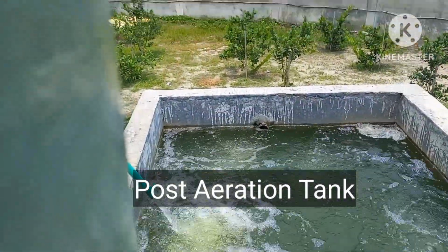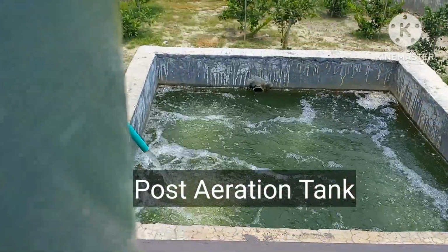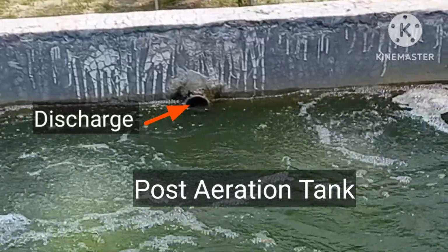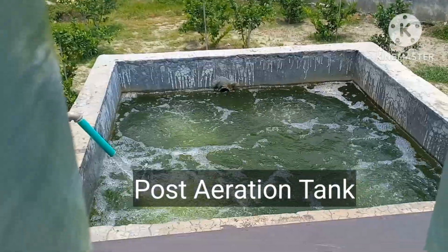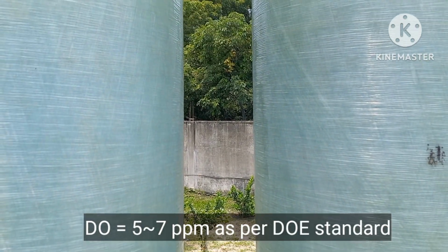After filtration, the dissolved oxygen is low and cannot meet the standard. So we need post aeration to increase the dissolved oxygen. After post aeration, we get the required standard of 5 to 7 ppm.